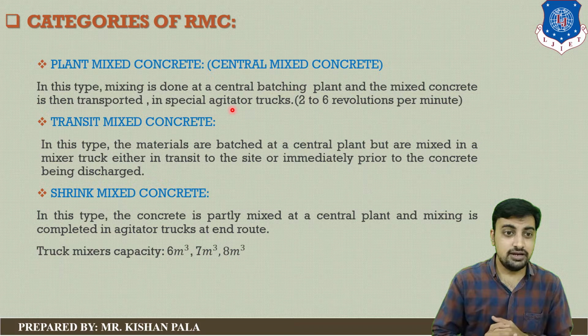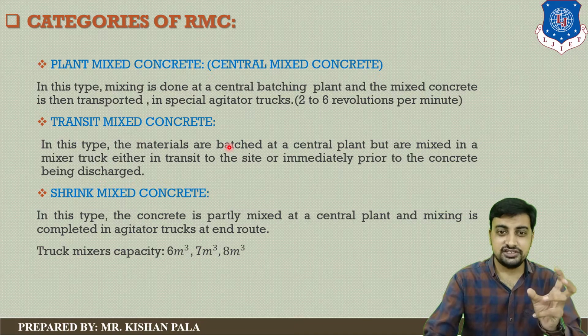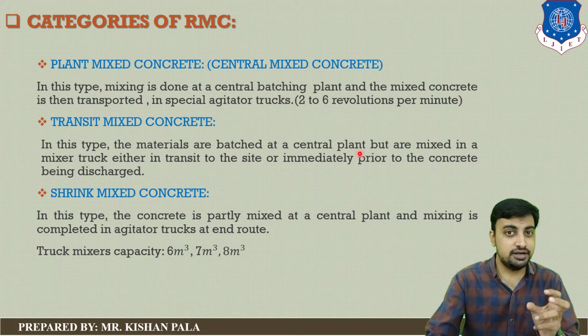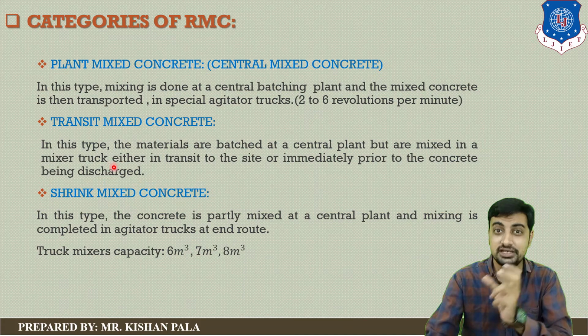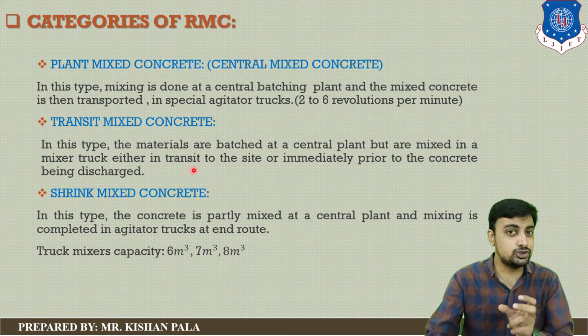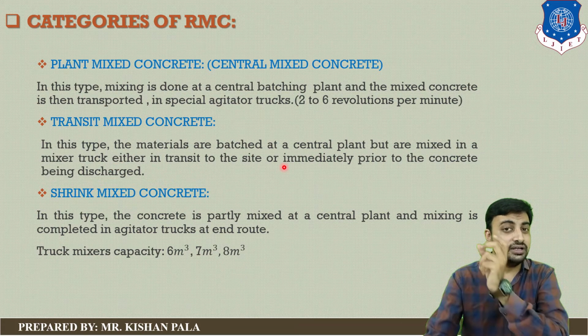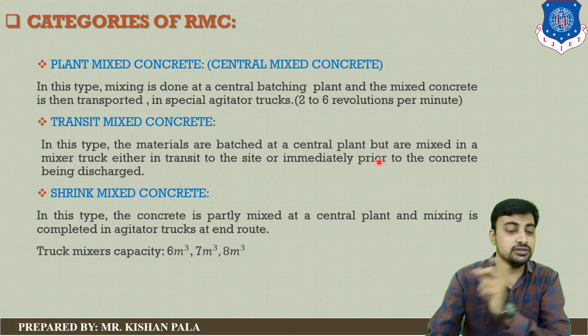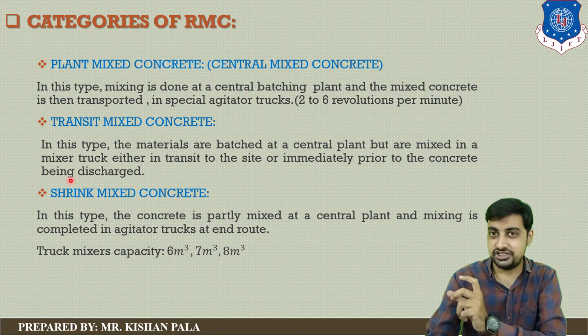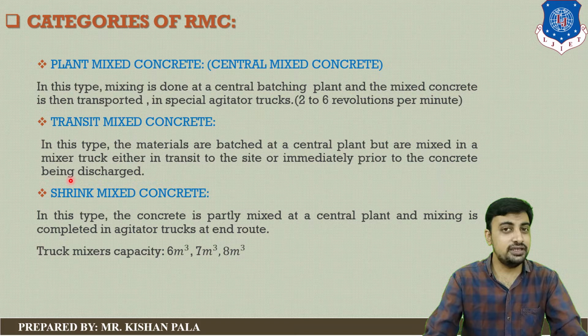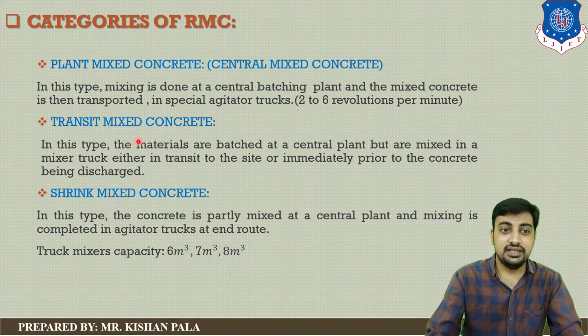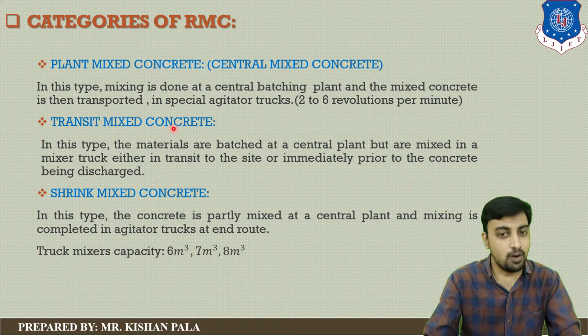And second one is transit mix concrete. In this type, the materials are batched at the central plant but mixed in a mixer truck in transit to the site, or immediately prior to the concrete being discharged. So this type of category is included in transit mix concrete.